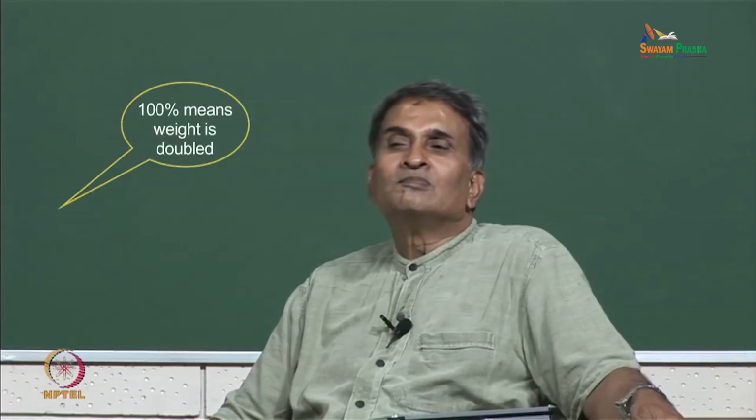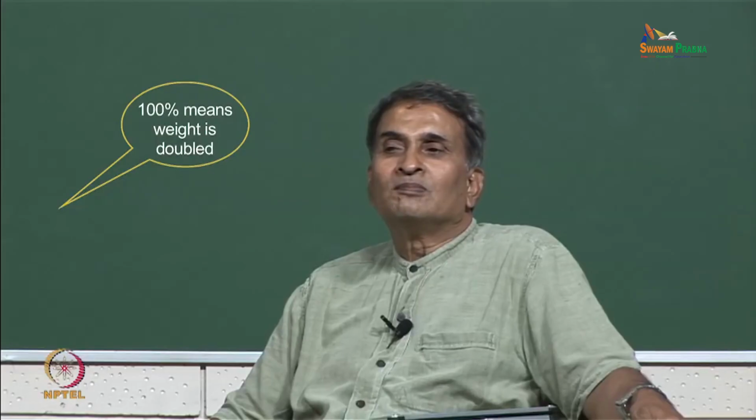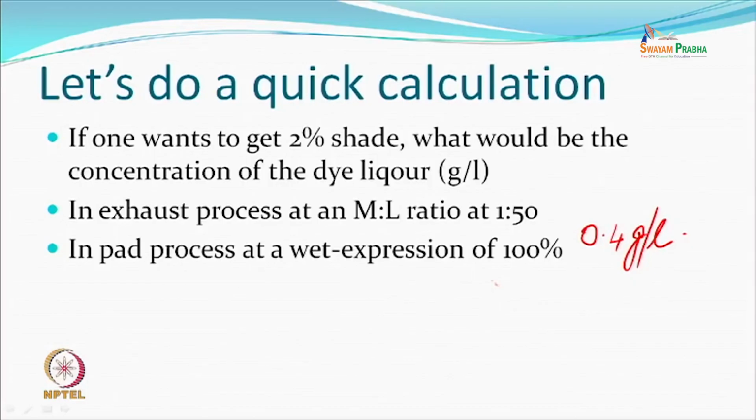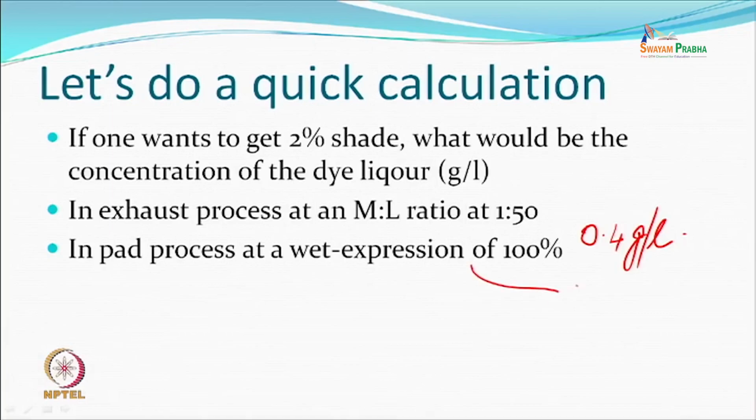If the fabric weight is 100 gram, it would absorb an equal amount of water. Right, or solution. So you take a 100 gram fabric, after padding it will become 200 grams, right? That's what is 100% expression. So what would the concentration of the liquor be when we really want only 2% shade? Shouldn't be that difficult. 20 grams per liter.